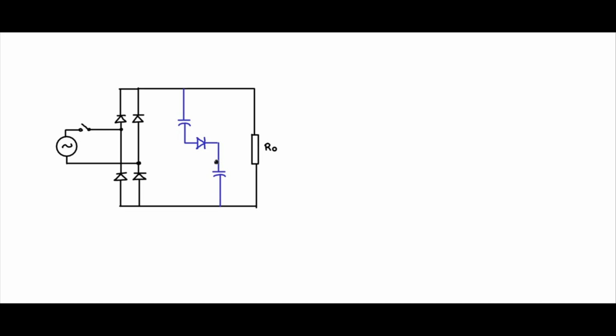Now when you want to discharge it, discharge each capacitor separately. So provide the discharge path. You put a diode in this fashion. So this diode will give a chance for this capacitor to discharge through the resistor in this fashion. And if I put a diode here, you will see that this capacitor can independently discharge through the load in this fashion. So while charging, you will see that the charge path is only in this way.